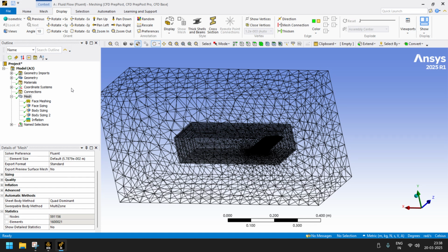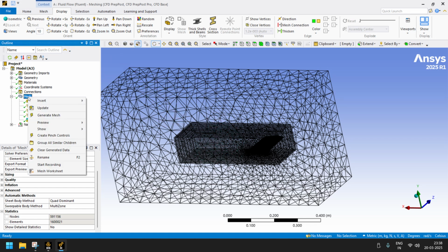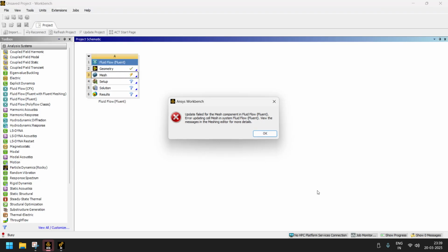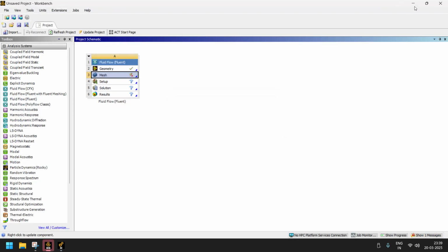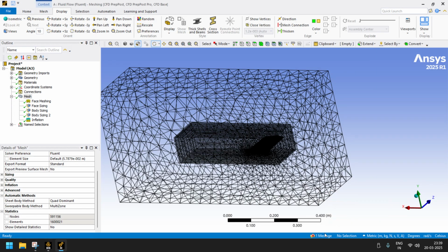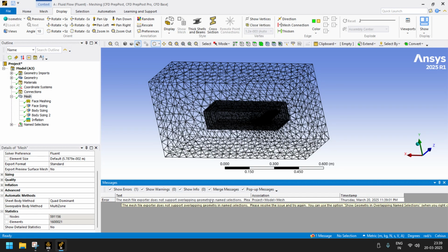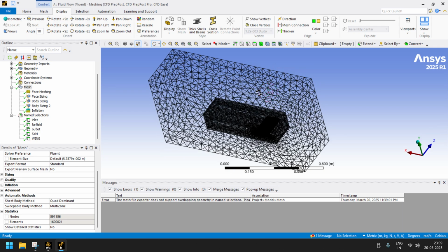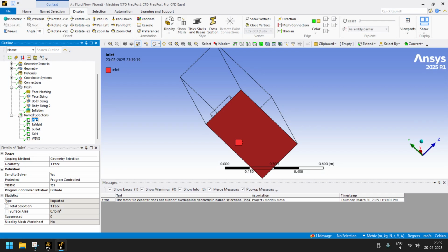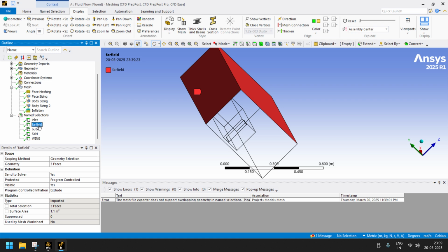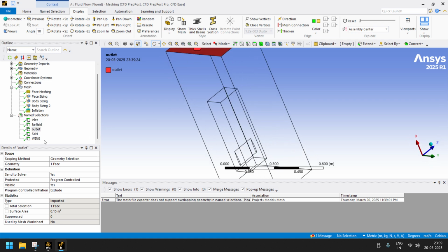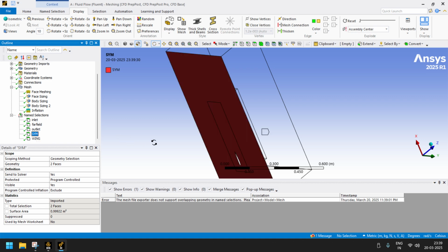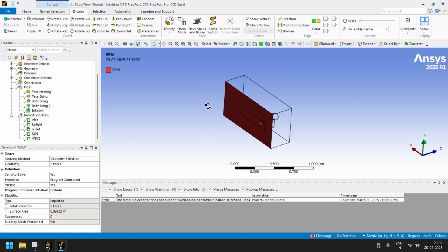So with this 16 lakhs mesh, we will move further for the simulation. Every time whatever changes you do, you have to generate, and at last you have to update. And you have to see what it's showing for the successful import. There is an overlapping of geometry named selection, that is, mistakenly I gave some name here, I think. For example, mostly it is the symmetry where the error is coming. Inlet is correct, far field is correct, outlet also only one, it is correct, wing also just 3, it is correct. Symmetry alone normally the error is coming.